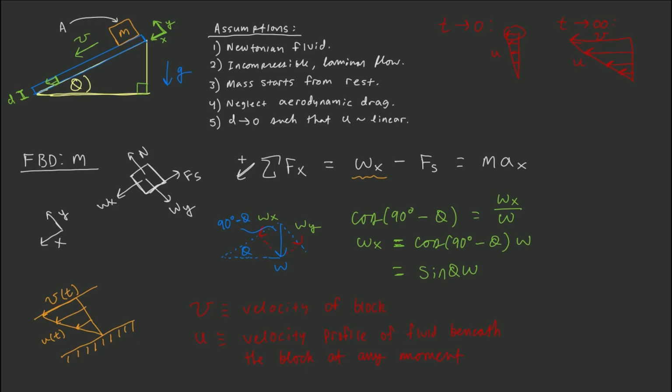So to write a more general form of Newton's law of viscosity, we would say it could be written as tau of yx is equal to mu partial derivative of little u with respect to y. And that will maintain our time dependence in a way that is consistent with this problem.